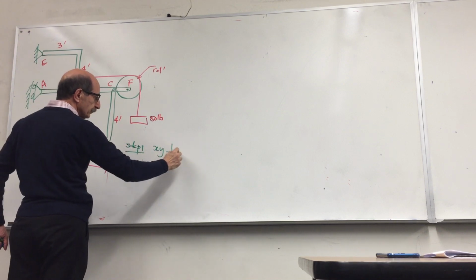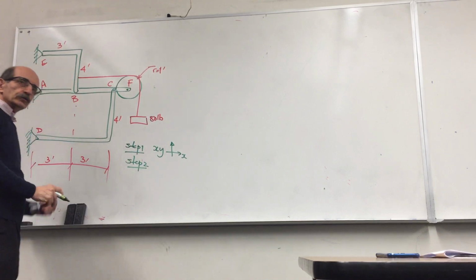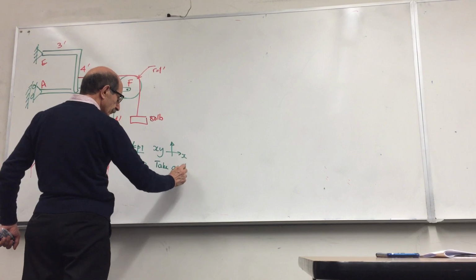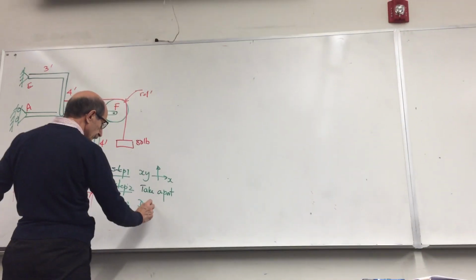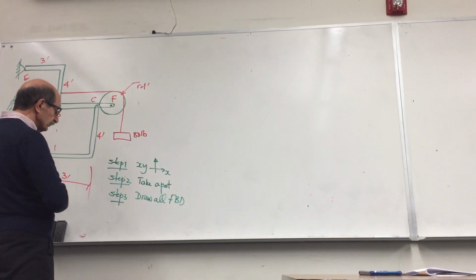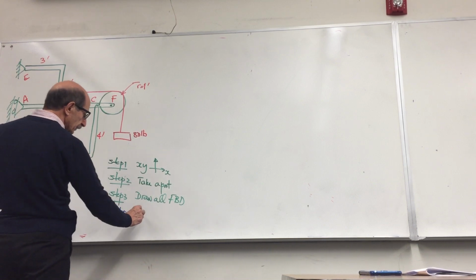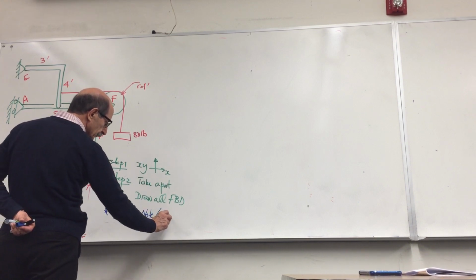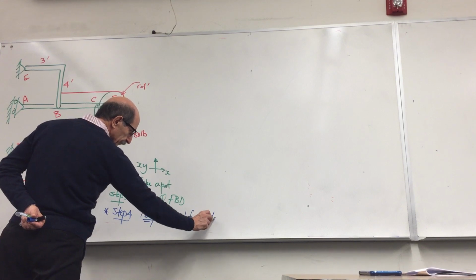Step two, you just take all members apart. Step three, draw all free body diagrams, and I had a special step, or maybe pseudo step, which was step 4, or part of step 3: note or watch out for two force members.